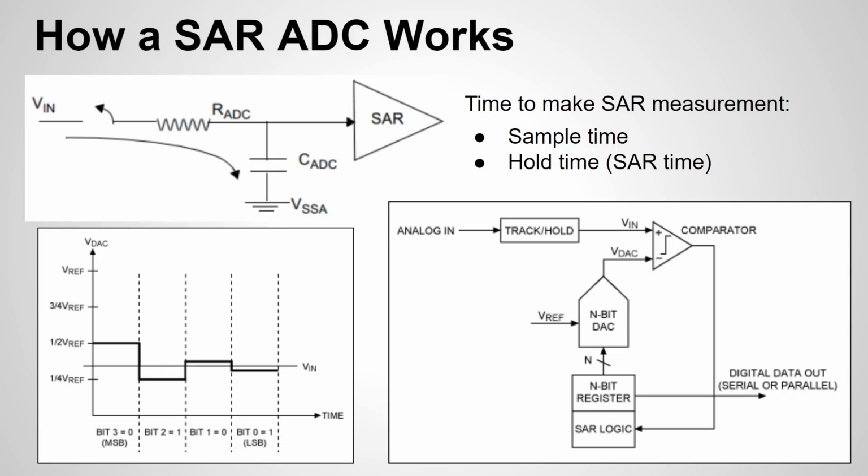So how it's done, and it's actually not that complex, is you have a comparator circuit, and the simplest way to do a comparator is an op amp. And what happens is a comparator takes two different inputs, a reference signal and an input, and compares them. Basically, you're saturating an op amp. Instead of having a feedback that controls the gain of the op amp, you're allowing the op amp to drive the saturation. Whether it drives to the negative rail or the positive rail for its output depends on which one of these is higher. So whichever one is higher will drive the output of this op amp.